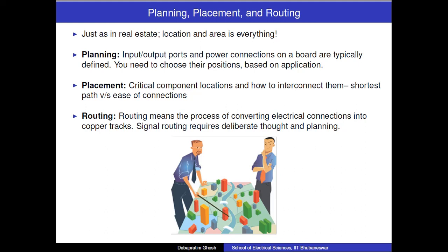At what point should my inputs and outputs lie? Should I place them all on the same side or on different sides? You need to think of how the PCB is to be used, and that will tell you a lot about how at least these things are to be connected, or at least the interfaces to the outside world. For example, the inputs, output signals, the power supply connections, and so on. At this stage of planning, what is inside the PCB is not of prime importance; that comes in the second step, that is placement.